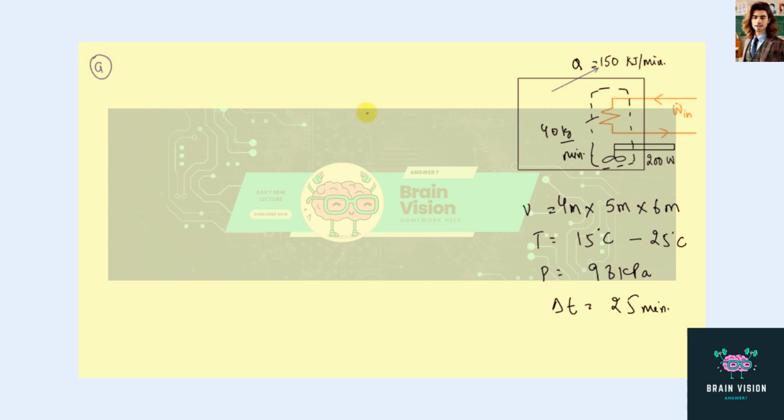Now to solve this problem, we'll be calculating the mass of air in the room. So m, by using the ideal gas equation, we can write this as PV over RT, taking the initial condition, so P1 and T1. Pressure is given as 98 kilopascal, so we can plug it here, and the volume is 120 meter cube, divided by R, which is a constant with value 0.287 kilopascal meter cube over kg Kelvin, times temperature T1.